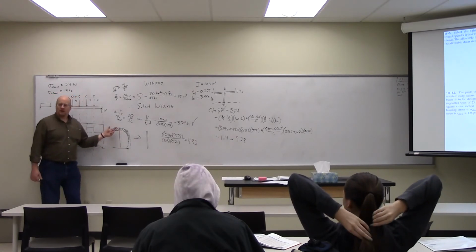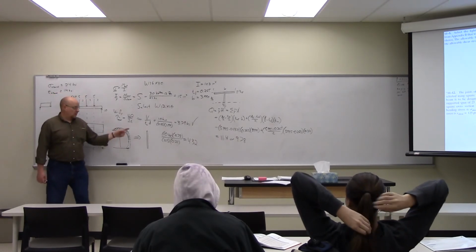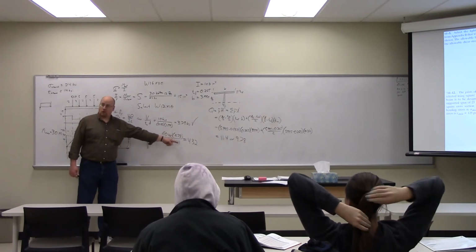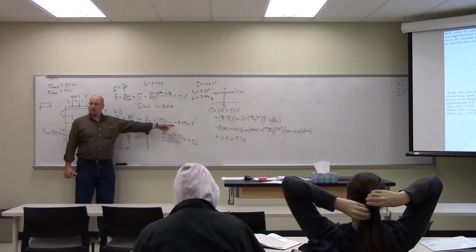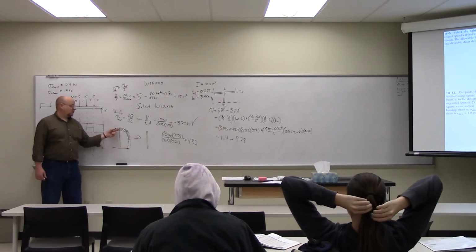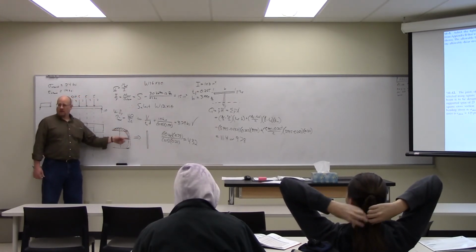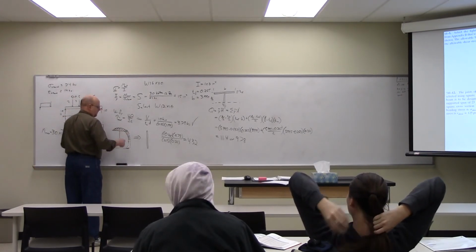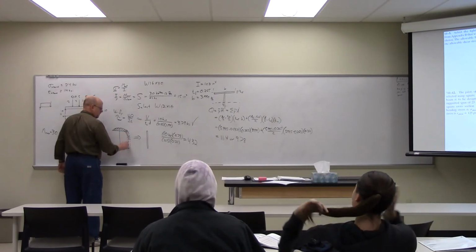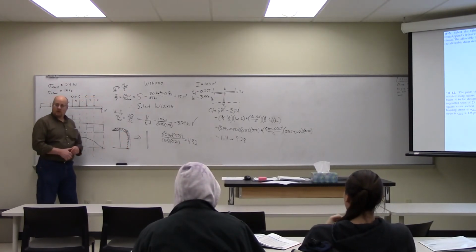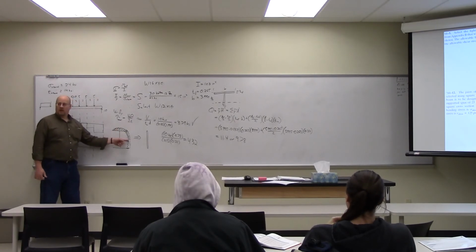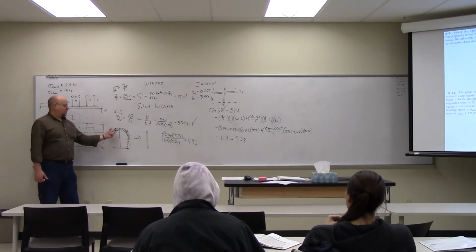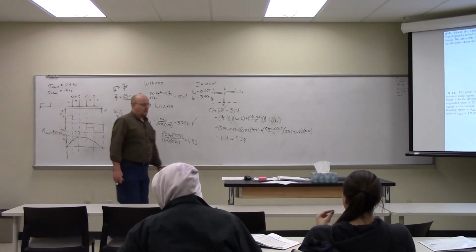Not necessarily. It depends on the characteristics of the beam. You can see in this case the actual shear stress is going to be larger than what we approximated. The approximation is that the shear stress borne by the flange roughly represents this out here. But in reality, the average came in sort of here, so that we're actually slightly below at the peak. Does that make sense? And that's going to depend on the characteristics of the individual beam.